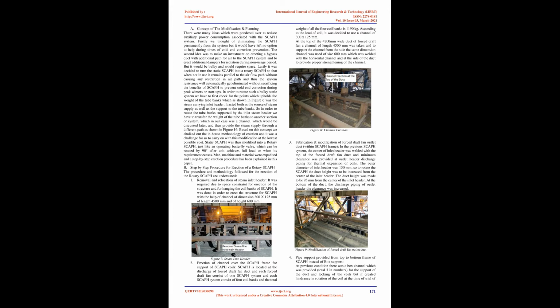Operational details of SCAF system. The operating pressure of the steam is taken at nearly 8 to 12 bar, depending upon the steam pressure available in the auxiliary PRDS, pressure reducing and desuperheating station, and temperature is taken with a minimal amount of superheat from saturation temperature at that corresponding pressure. Forced draft fan delivers the air at ambient temperature and at a draft pressure of 150 to 220 mmWc, millimeter of water column. Generally, 20 to 25 mmWc pressure drop occurs in the SCAF due to its complex geometry.